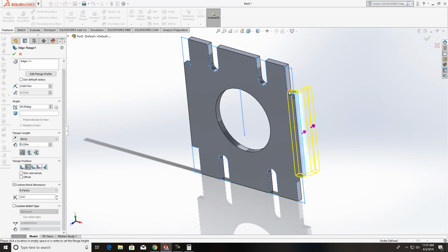And then the relief. This is going to be like a little relief back up in here. We got to set that again. Custom relief, and you want the obround on this one, and I'll show you the difference. If I hit rectangle, if I hit obround, it's going to make a little bit more sense right here.